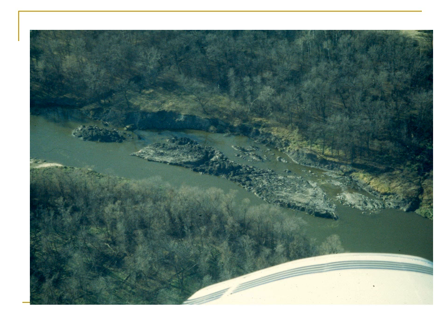The senior design students in this case were able to use the Swedish circle method to estimate the soil strength because they knew the actual slip surface, so they could get the soil geometry, and the one unknown that they actually had was the strength of the soil, because they knew the factor of safety.